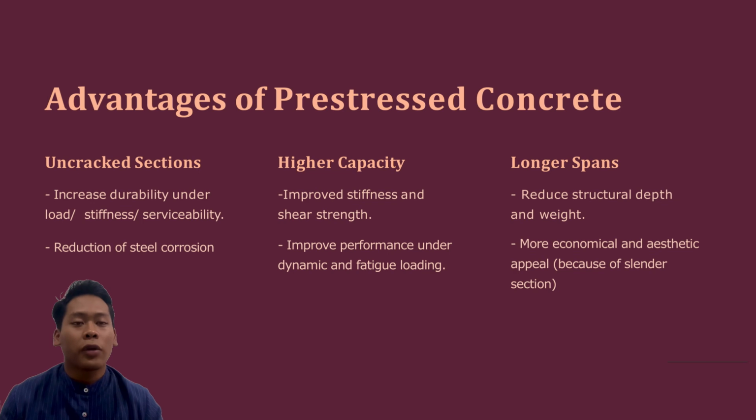Moving on to our next slide, which is the advantages of pre-stressed concrete. For the first one, uncracked section. Pre-stressing will help concrete to maintain uncracked sections by increasing the durability, stiffness, and serviceability under the load. By preventing the cracks, it will reduce the risk of our reinforcement corroding.